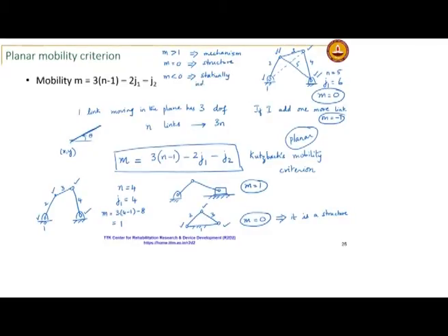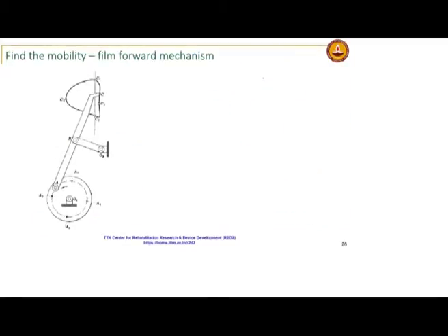So, you need more than the static equations of equilibrium to solve for such a system. So, again all of these you would first do the kinematic diagram, and you can see it is only a 4 bar. So, obviously its mobility will be 1. Okay.